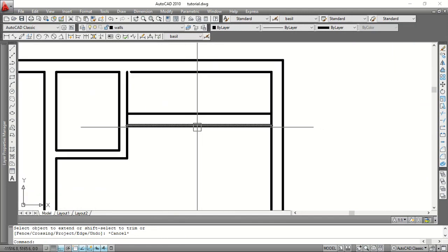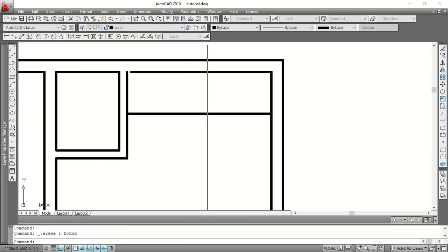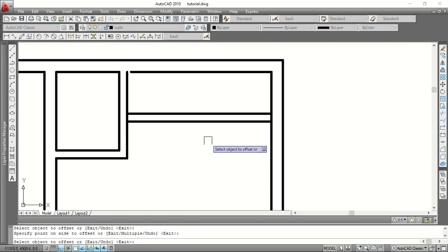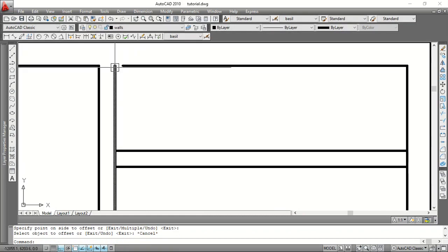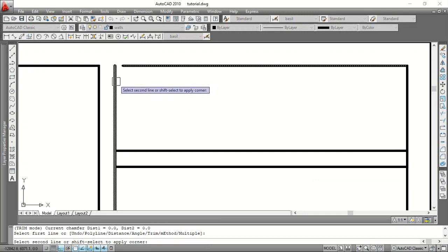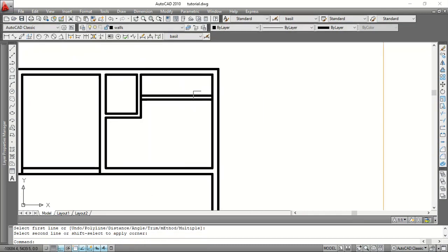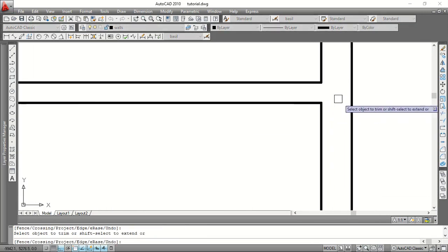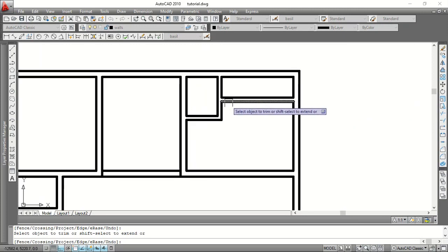Same thing again here. I don't need this wall to be 225. I need it to be 150. So I take it off, offset 150, enter. Good. So you see, we have the same problem. So I pick back my chamfer, click the first, click the second, and that's all. All right, so we have perfectly done this. Let's trim at this point, you trim at this point.